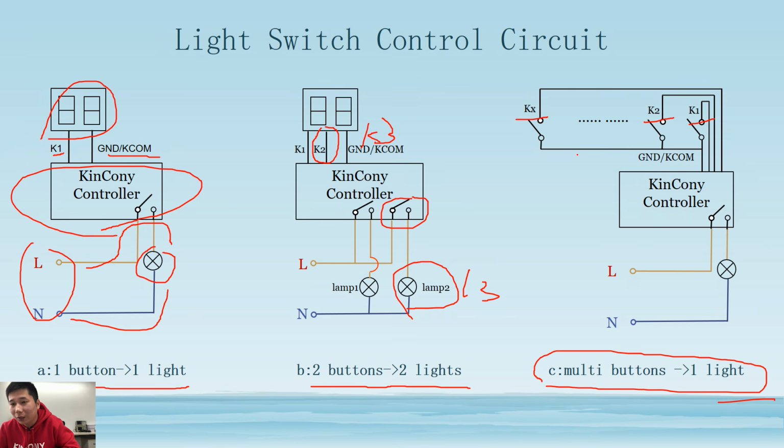You just connect this KinCony together, and on the other side you just connect this line together. This is all together, used by just 1 digital input. This is just DI1, this is just DI1. So not DI1, DI2, DI3, DI4, only DI1. So all of this is connected together and connected to the digital input.